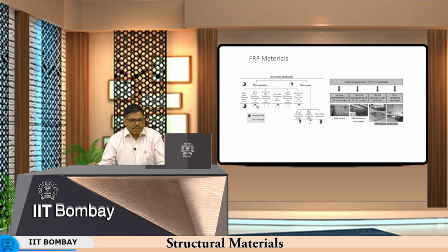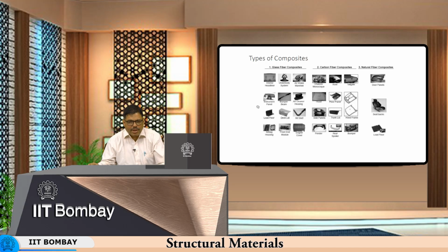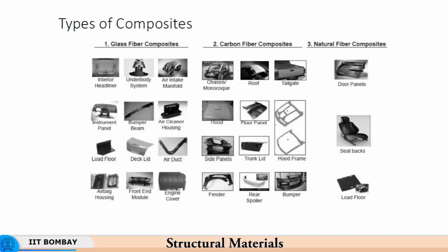Then we have glass fiber and fiber reinforced plastics, polymers basically. So we have thermoplastics and thermosets as artificial materials, and these are reinforced by different kinds of fibers, be it carbon fiber or glass fiber. Now glass fiber is used for, let's say, transmitting signals to large distances. So in that sense they are functional materials, but glass fibers used for structural application as shown here are also structural materials. So we are leveraging the structural strength of glass to form members of a composite. Glass is a part of a composite.